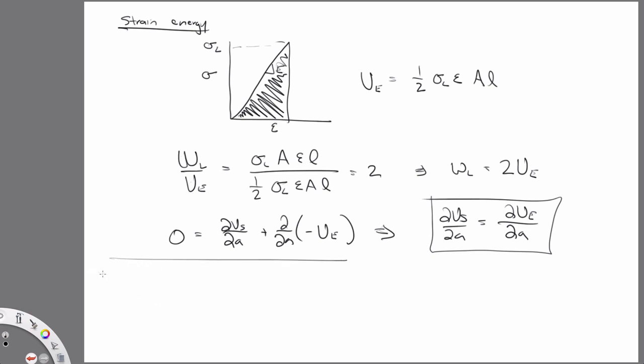So we're going to define our energy associated with creating new surfaces as 2, because there are 2 sides to a crack, 2 surfaces on a crack face, right, a top and a bottom, times 2A, because that's the length of our crack, times some specific surface energy.